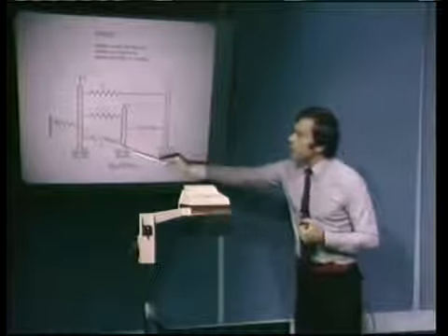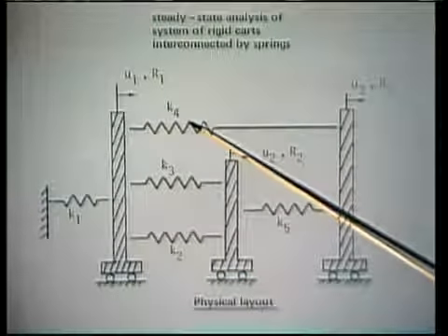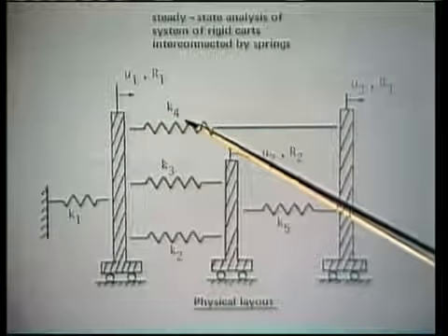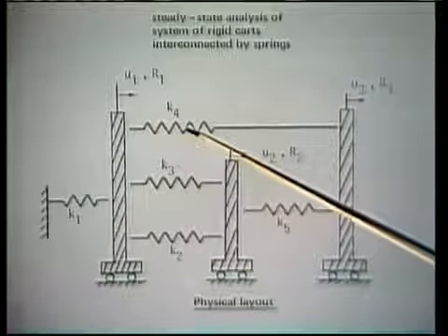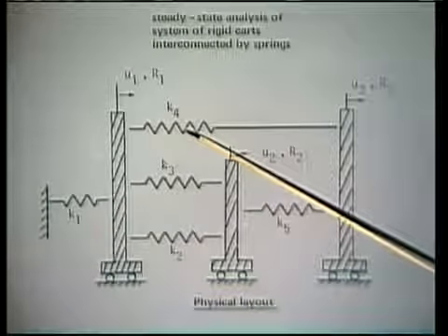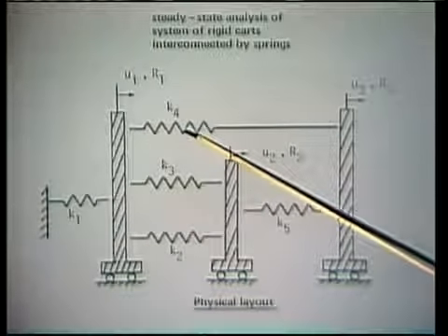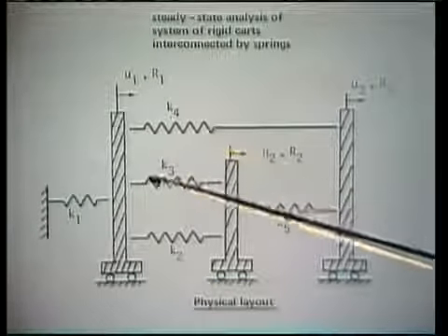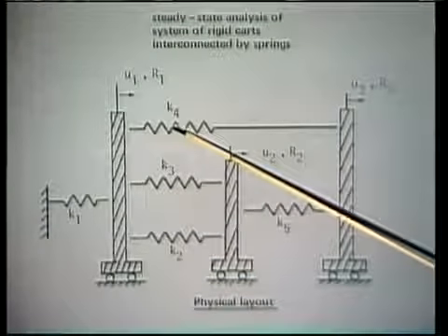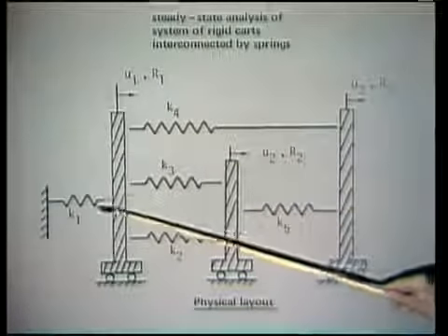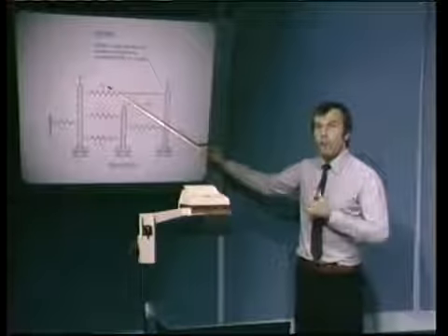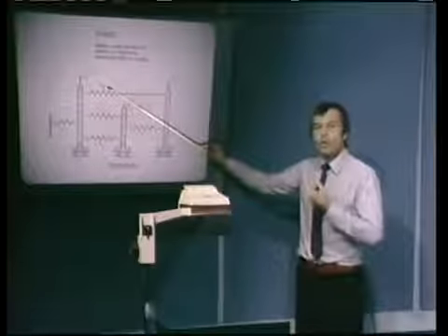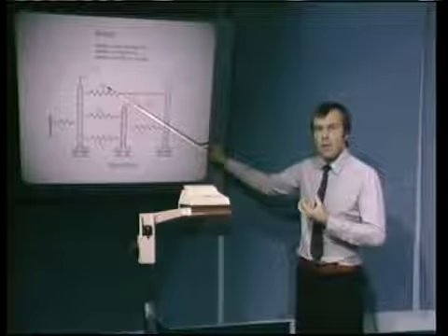Notice that these springs here are our finite elements, if you want to think of it that way. A very simple set of elements. In a more complex analysis, these springs here would be plane stress elements, plane strain elements, three-dimensional elements, shell elements, and we will be talking how we derive the characteristics of these elements. And we will, however, interconnect these elements, these more complex elements later, in exactly the same way as we connect these simple elements. So the connections between the elements are established in the same way, and the solution of the equilibrium equations is also performed in the same way.